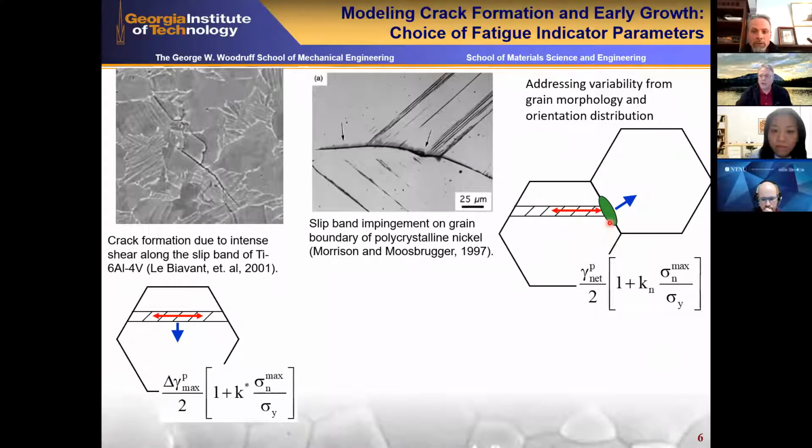But typically the cracks will form due to disruption of the grain boundary and a release of the constraint on slip in the adjacent transgranular region. So the cracks grow up the transgranular slip plane away from the interface. And you see these typically in the literature where people have done SEM images of failure sites.